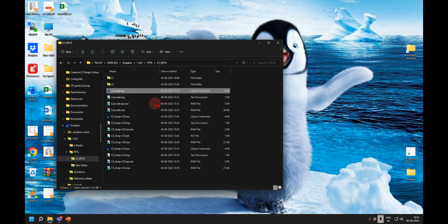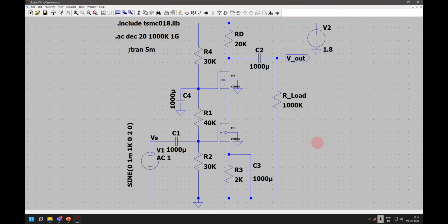That last capacitor, is it acting as a DC block, or is it also acting as a load? No, DC block. I'm taking the output. That is a part of pole creation also, right? Wherever you have connected Vout, there is a capacitor. That is just to block the DC, and it will create a pole with the load resistance. So you have to be careful with those values.